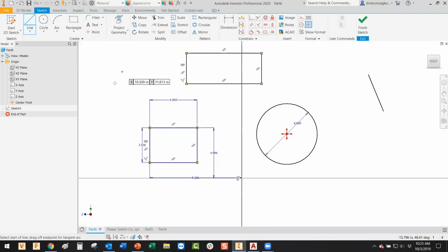Same with the line tool. We just draw a straight line going like that. You can see a constraint's about to be made with that black line going horizontally across with that red line right below it. That's automatically created as well. And if you don't have a constraint and you want to create a constraint, let me go ahead and delete this parallel one, for example. You can go ahead and manually create it up here.